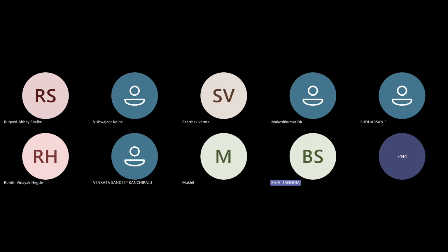In case the gearbox is coupled via a primary drive, you can calculate an overall gear ratio, that is multiplying the ratios from the end to the start, and put it directly into the transmission system.